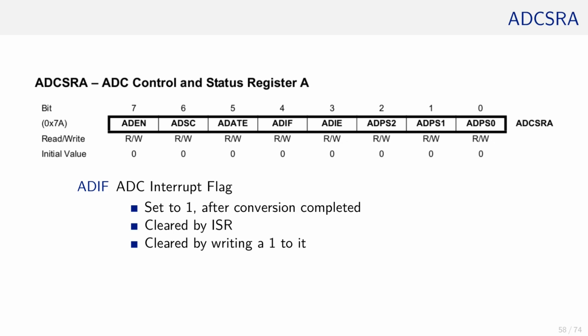And the last 2 bits, ADIF, is the ADC Interrupt Flag. Therefore, conveniently, a conversion can be started and other parts of the program can be executed while the conversion is in progress. Once the value is ready, the CPU is informed about that event and an interrupt subroutine handling the reading is executed.